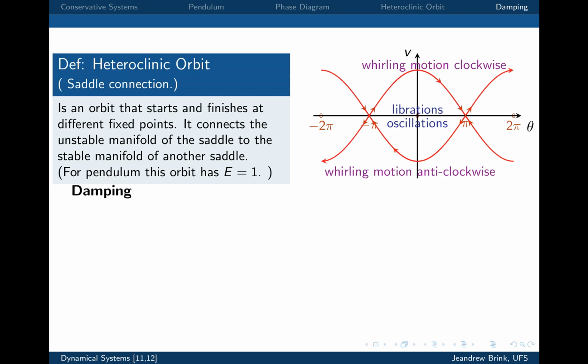And there's a lot of money that actually goes into how you store energy. One way of doing it is you basically have two heavy objects that spin. When you have a lot of energy, you spin these objects up. The ideal thing is you want them to continue spinning and not lose energy due to friction. The thing that spins has magnets, and when you want to take out the energy, you put a coil around it. You can then pull out that energy by simply directly making electricity. They call that a flywheel.